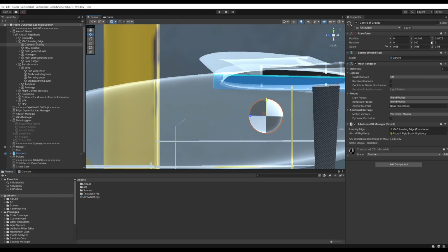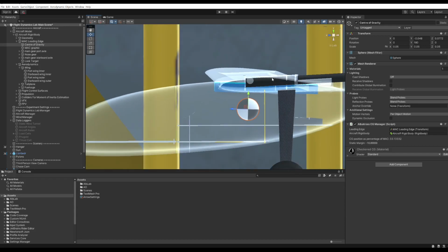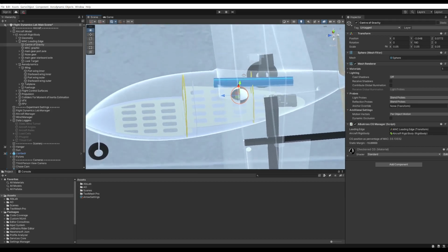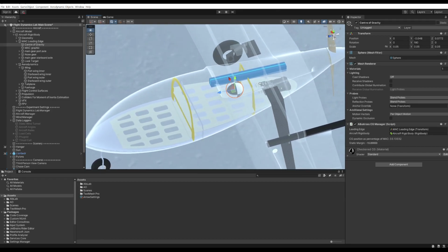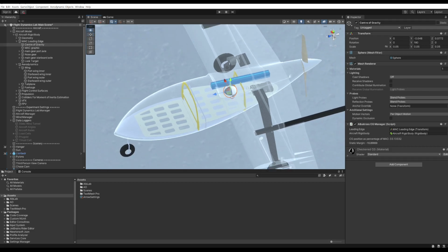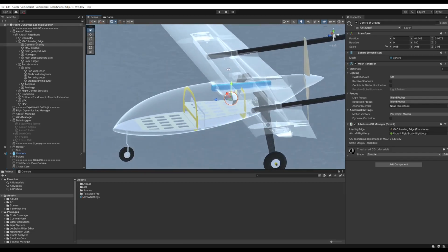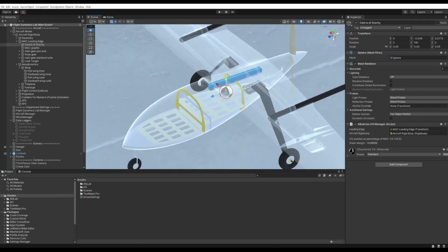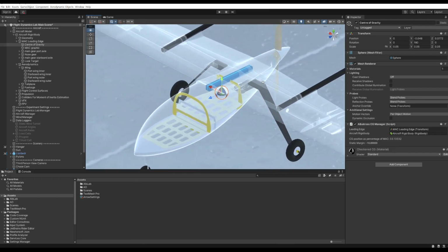So the mean aerodynamic chord length is around 24 centimeters, so around 7 centimeters is about quarter chord of that, and just eyeballing that, our centre of gravity there is at about quarter chord of the mean aerodynamic chord. Measuring things in simulation is actually quite easy. When you've done this in real life with a ruler on an aircraft with no flat surfaces or anything else, you realise how hard it is, and actually having a digital model of an aircraft where you can move things around is a much more convenient way of dealing with geometry. But ultimately in real life you have to check it against what it is in physicality.